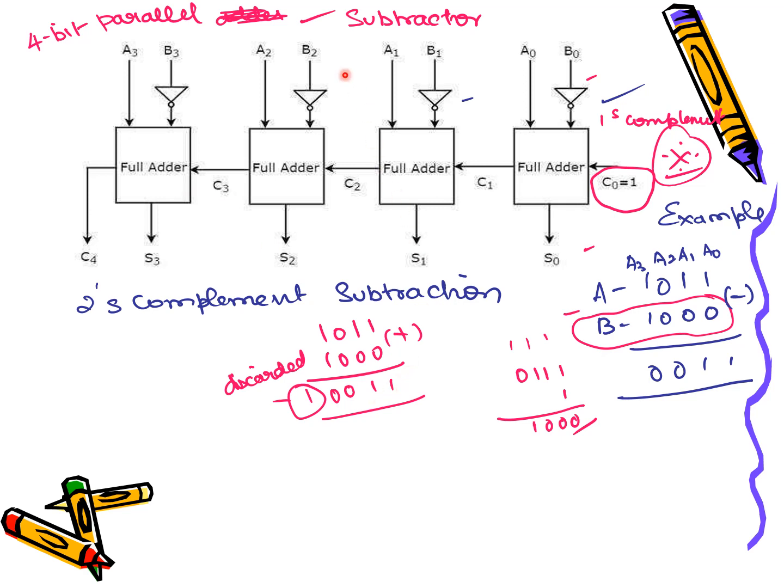So even if you try to perform a subtraction operation for these two sets of input signals, it will be performing an addition operation, but for that it has to satisfy the condition of two's complement. So that would be provided with the help of what? By inserting an inverter over all your subtrahend bits, and forcing the initial carry to be 1. So the only changes are the initial carry to be 1, and all your B input signal bits have to be complemented. To take the complement, an inverter is enough.